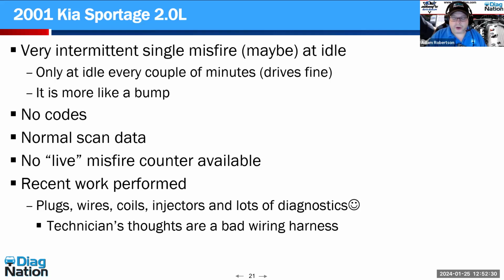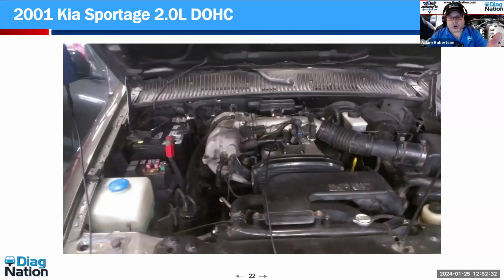I went down and showed up. There's the car. You know what's kind of tough about this? This has a waste spark ignition system that's under this tube. At the end of this tube is a mass airflow sensor. I can't get to all the coils unless I pull that tube off. If I pull the tube off, the engine won't run because it needs that mass airflow sensor. But at any rate, this should still be pretty simple.